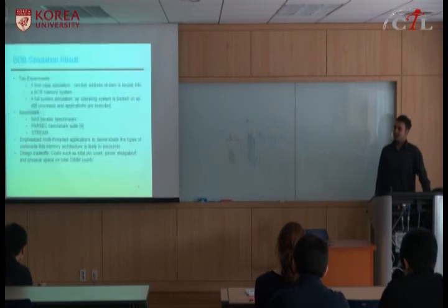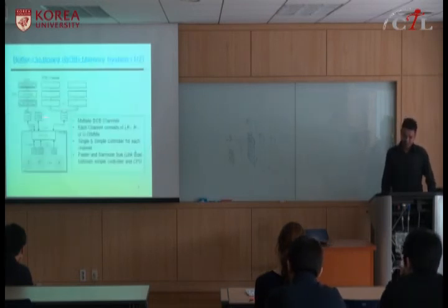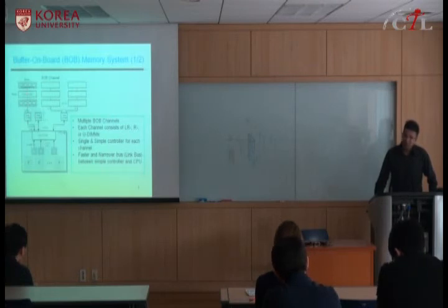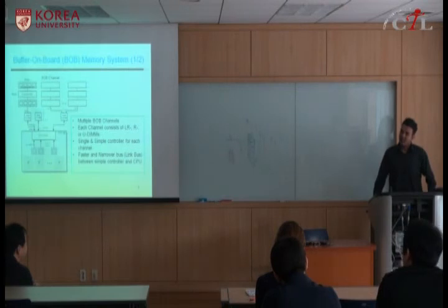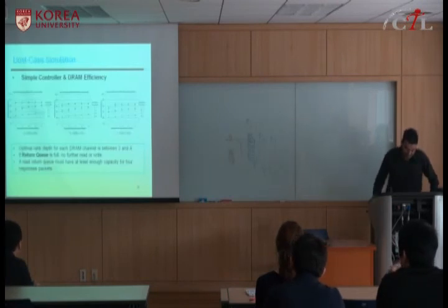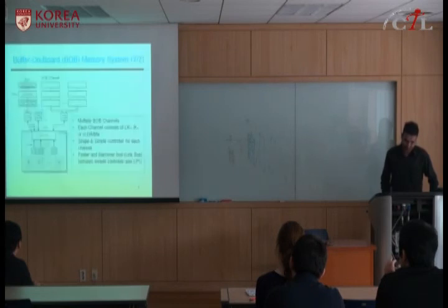Okay, let me ask you a question. Here, the link connecting each DIMM, is this point to point or both? Yes, this link is a bus. Okay, so this is an old technique. They don't use this kind of bus technology anymore. Actually, this is very conventional, but they try to find the optimum values for this structure, like how many ranks should be here.